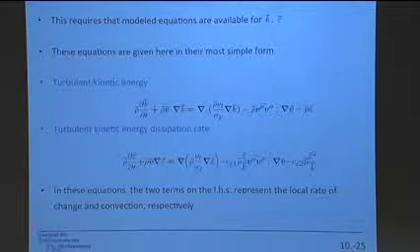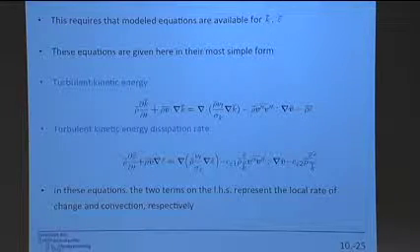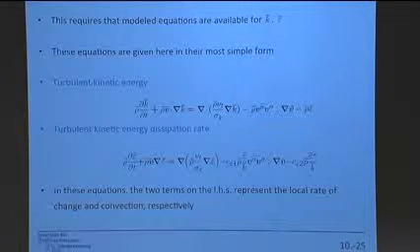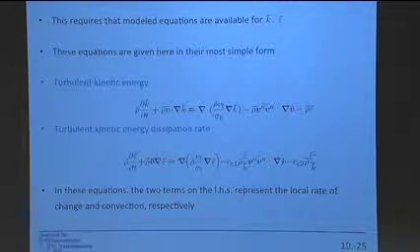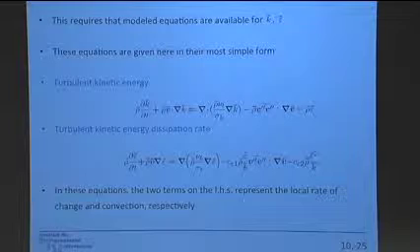And then you get a term like this, which, if you integrate it over all space, over the volume of this room, would not go away. You would find that it's typically positive. And so this here is a production term. You see this is the velocity gradient tensor, which shows you that when you have shear velocity gradients, then you produce turbulence. Okay, turbulence production is related to velocity gradients.